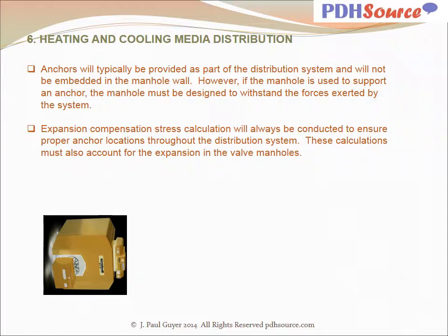Anchors will typically be provided as part of the distribution system and will not be embedded in the manhole wall. However, if the manhole is used to support an anchor, the manhole must be designed to withstand the forces exerted by the system. Expansion compensation stress calculations will always be conducted to ensure proper anchor locations throughout the distribution system. These calculations must also account for the expansion in the valve manholes.